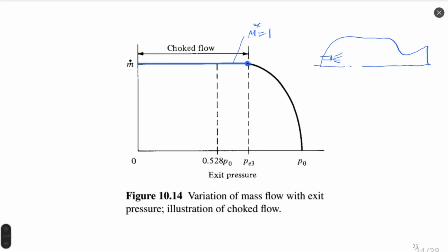For example, we are injecting this propellant with quite a significant pressure ratio. Our chamber pressure is at least 2 times smaller than injection pressure. It means that we can keep mass flow rate constant independently of the pressure inside the chamber. So you can choose any pressure inside the chamber.